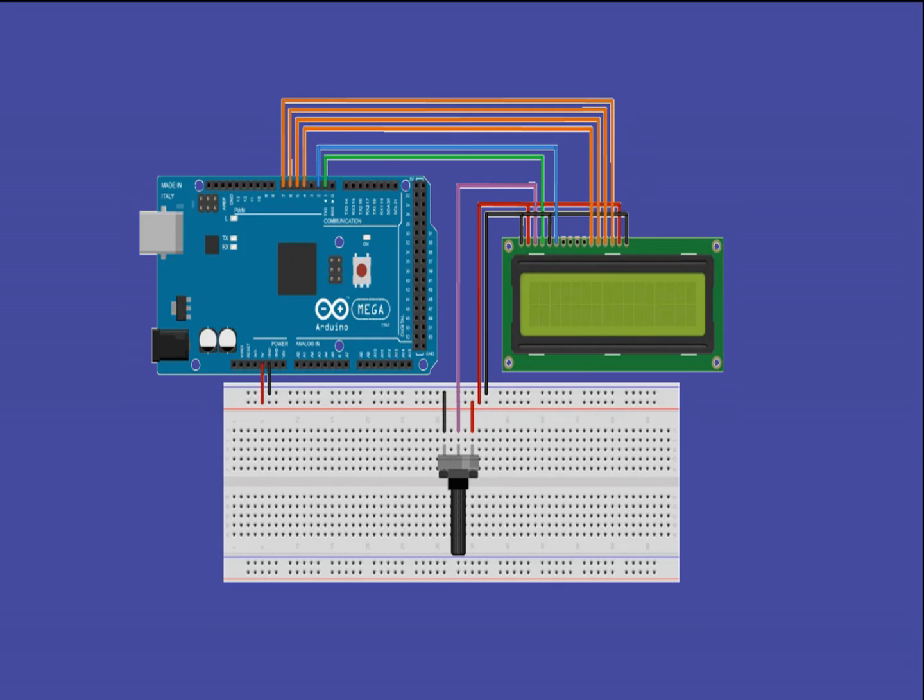We are using a potentiometer because it enables us to easily fine-tune the contrast by adjusting the input voltage from 0 to 5 volts. All you need to do is simply turn the shaft on the potentiometer until you reach a brightness on the LCD that you are satisfied with. Don't start turning the dial right now, as you need to wait for the code to be uploaded.